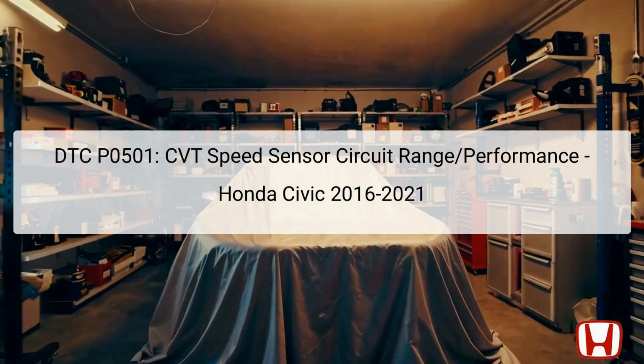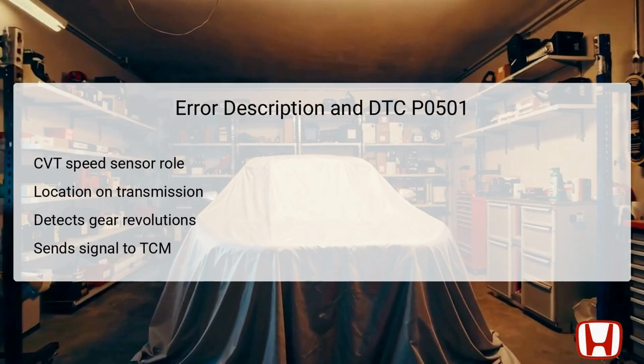The malfunction could stem from various sources, including the sensor itself, wiring issues, or faults within the TCM. It's important to address this DTC promptly to maintain proper vehicle performance and safety. The CVT speed sensor plays a critical role in the function of the vehicle's transmission system. Located on the exterior of the transmission housing, it measures the number of revolutions of the secondary driven gear. This information is sent as a pulsing signal to the transmission control module, TCM. The TCM processes these pulses to determine the vehicle's speed.